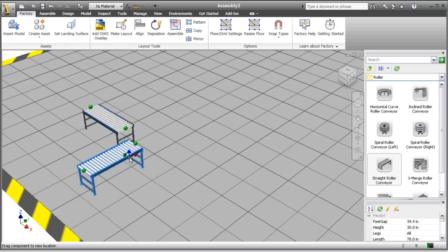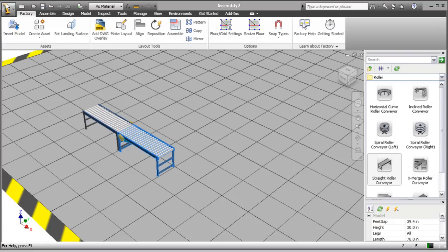I want to assemble the same component again, so I am going to simply drag it around to locate the second instance. Each component has a connector assigned to it that provides a logical connecting point. As I drag the second instance close to the first, you can see that their connectors begin to snap to one another. A preview rubber band first appears, and then as I drag closer to the component, it snaps into position. To finish placing additional components, I simply press Escape.